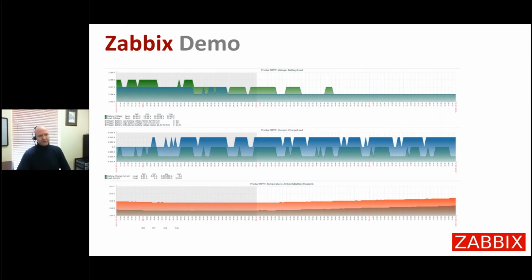So, for instance, if you look at these graphs over a week, a month, a year, or many years, the things that will start to come out of that data are, you can see battery age over many years and when it's getting ready for replacement. If you start seeing events or thresholds being crossed, such as low battery alarms or load disconnects, which means your site is having trouble staying operational, you can start to anticipate a battery replacement. If you can see temperatures during a certain period in a certain region rise above 50 C within the cabinet, you're going to know that you've got some high temperature issues that may affect the operation of the equipment.